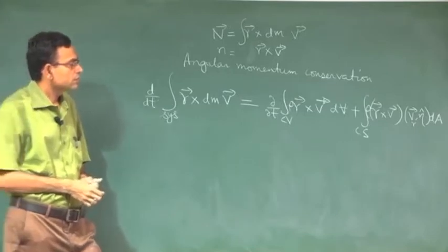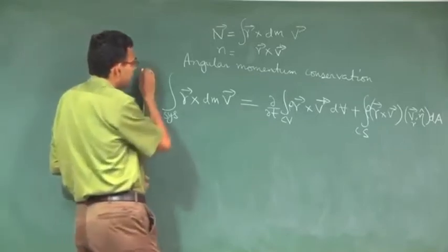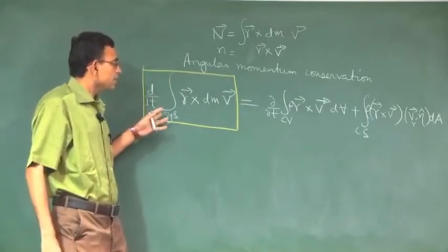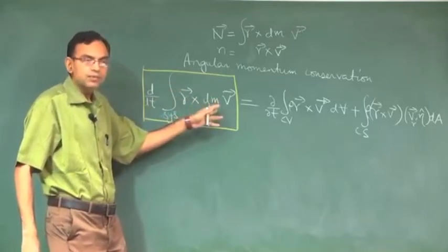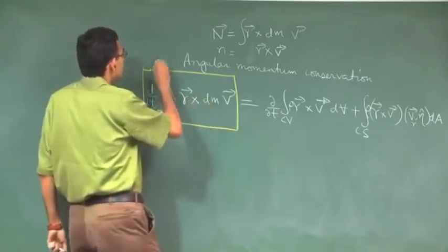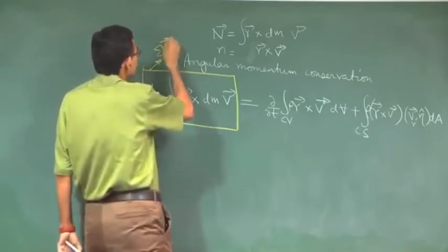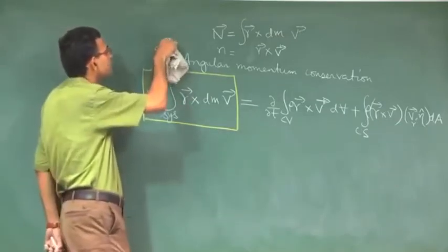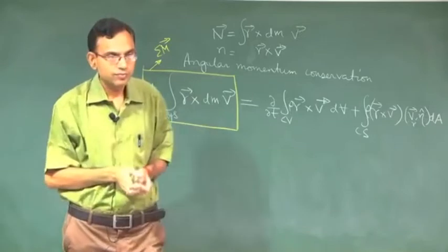Now only one step remains before we come up with an expression. So this is the net rate of change of the moment of linear momentum of a system. So this by definition is what? The resultant moment of everything, including the moment of forces and also couple moment, whatever, resultant moment, say M. This is essentially Newton's second law for angular motion.